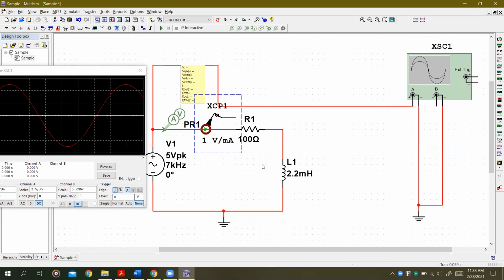Okay, so that means we have to find a method to convert a current into a voltage so that we can read it on the oscilloscope. So do you get that part? What this does is, when a certain current passes through this line right here, it will output a voltage.